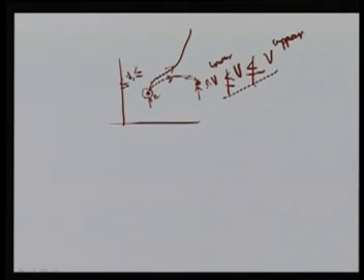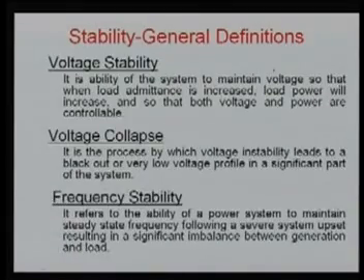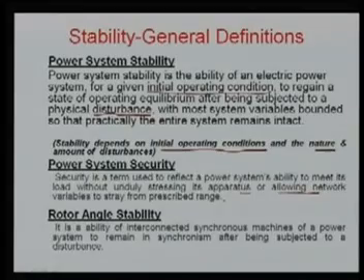So, it is one step ahead, where we have to check the operating limits as well, that it should be well within limit. So, that is your power system security. Already we defined power system security and gave the different kinds of security in terms of line or megawatt security, reactive power or voltage security, and then we gave the several states based on security: normal state, secure state, alert state, emergency state, restorative, and so on. So, you can see this security is one step ahead of your stability.